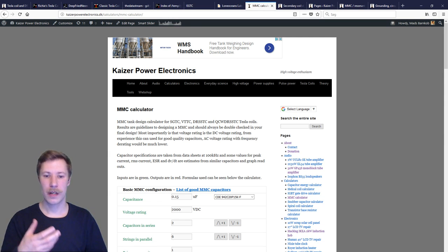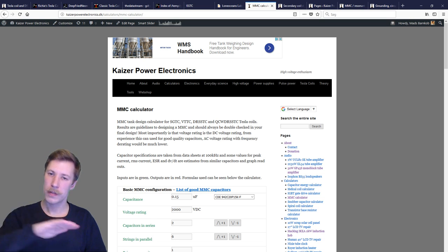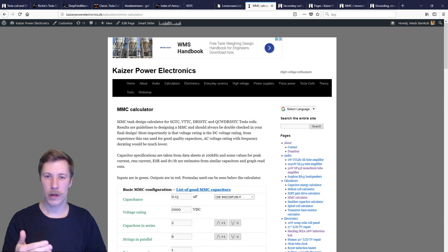So you can suddenly have loose windings that will overlap, and as soon as you get something that is not even on the surface of the secondary coil, that becomes a problem. You will suddenly have a small corona discharge, and suddenly that will attract a spark, and you will burn a hole in your insulation, and it's done. Then you will have to make a new one.